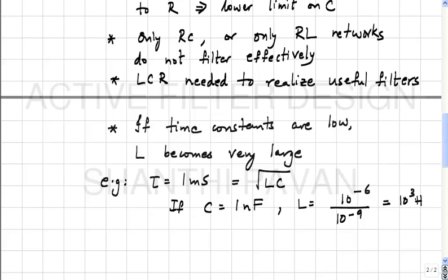For example, a lot of biomedical signal acquisition, right? Stuff in our body happens at a few hertz, correct? Whenever you are trying to acquire biopotentials, there is a big interferer in terms of the 50 hertz, or 60 hertz if you are in other parts of the world, floating around everywhere. You are trying to acquire 20 microvolts from say an EEG pickup, and you run a cable to the machine, and it's not inconceivable that the cable picks up a few millivolts of 50 hertz noise. You need to get rid of that, right?